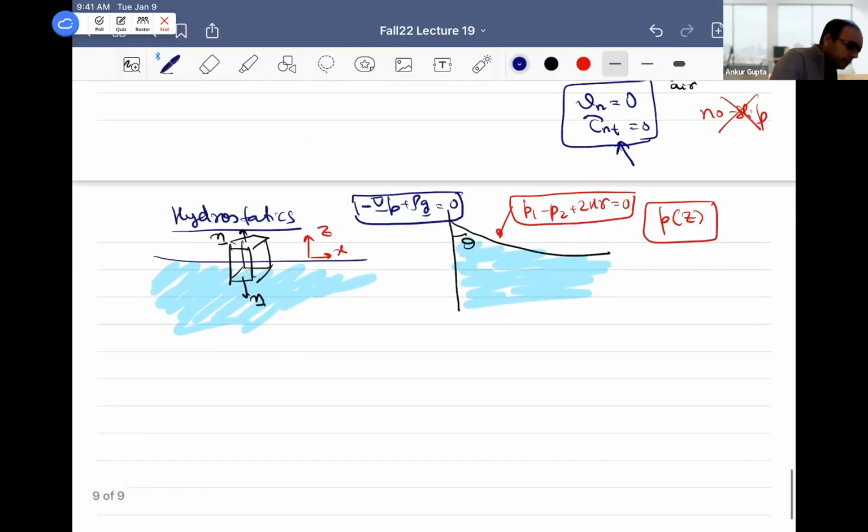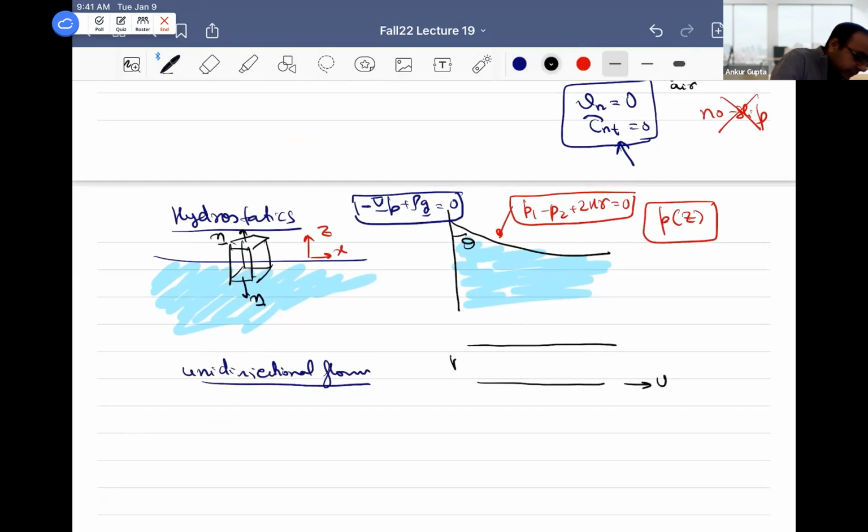All right. Then we said, okay, the next is unidirectional flow. So the model problem is, I would say, the one that you did in your homework, which has P1, P2, and you had something like this, or maybe I'm getting the velocity profile wrong, but I hope you can see there was a superposition of this plus a velocity profile that goes like this. So linear plus a quadratic, which you did in your homework, and then you can change the pressure gradient and velocity directions to superpose that. And this is a good problem.